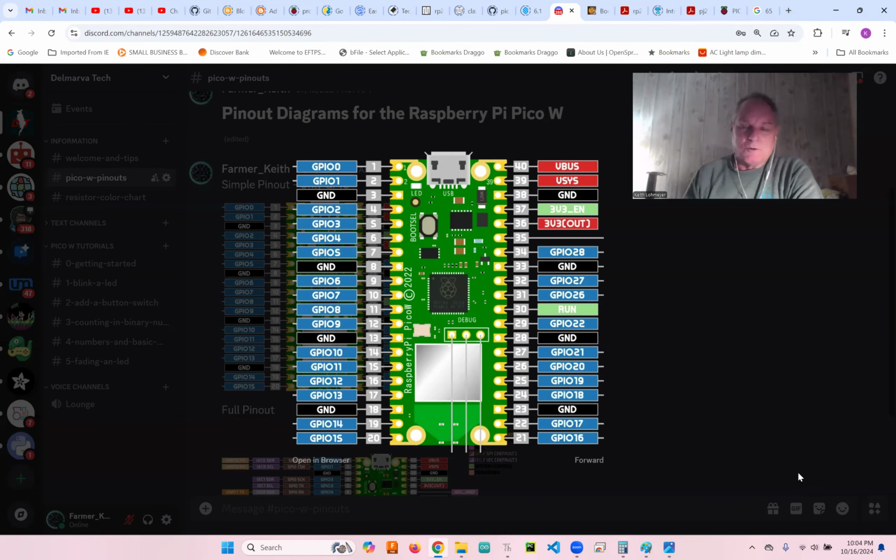So what I did was I used the ground here, and I could just plug it right into the board on the empty row of pins I had here. So you've got ground, and then 21 is going to be echo, 20 is going to be trigger, and 19, I'm just setting a pin to output and making it high, and that supplies power to the sensor. I've done that with a couple other sensors, I forget which one, the temperature sensor maybe.